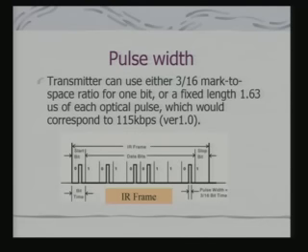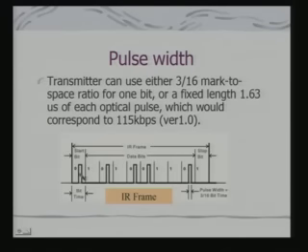So, if we look at a simple example of RS-232C, which is the most common asynchronous protocol, normally the signal lines are in what we call marking state. Marking state is typically high state for the signals, and then when a data transmission is to start, that bit goes down. So typically you have got a start bit.